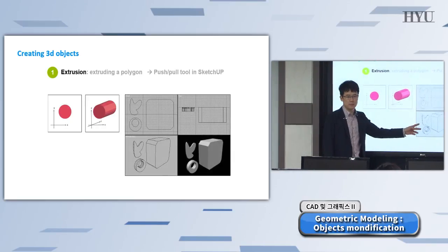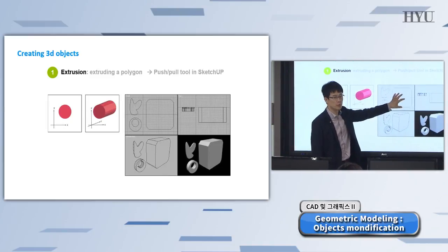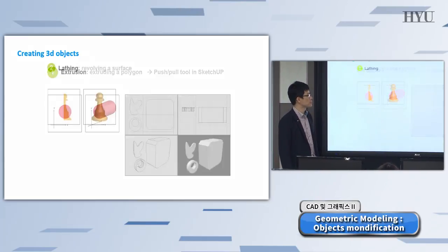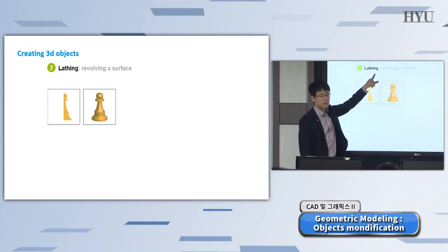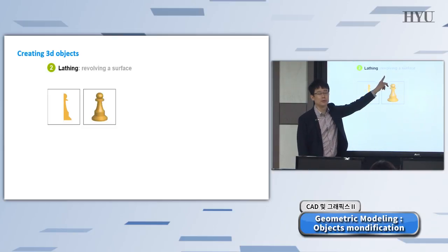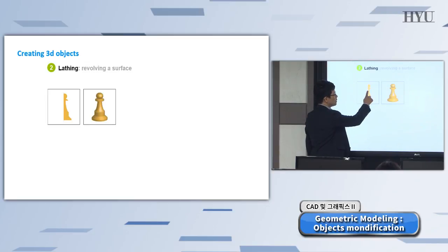This is the 3D Max interface. You can draw anything in top view, and you can make that 3D by using extrusion. Next one is revolving. Lathing, this is actually the term in 3D Max, lathe, okay? But usually it's revolving. One axis, okay? A linear axis, and one single section profile. Simply revolve it, and you can create this kind of object.